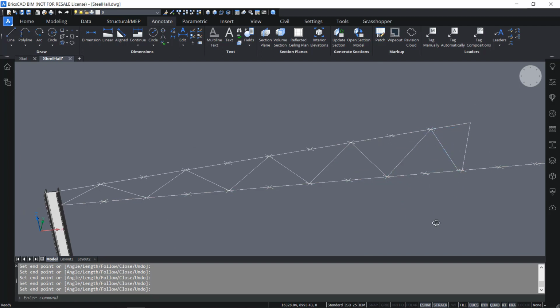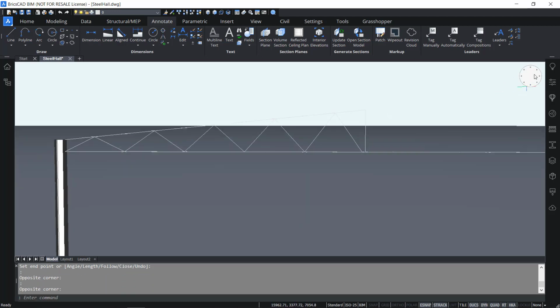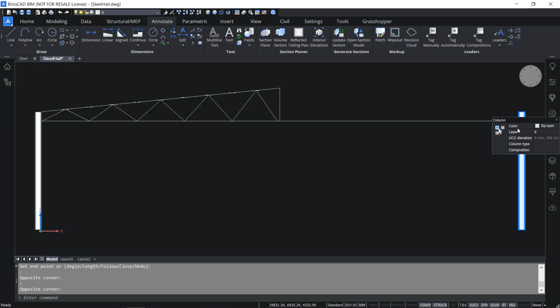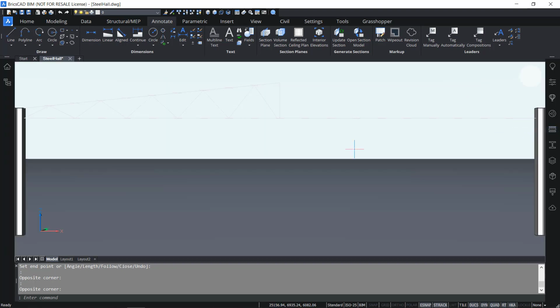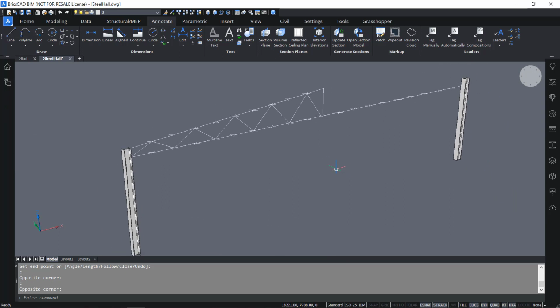Just like this, so that you actually created a truss. I can show you again if I go to the front view and put perspective back off. You will see that now I created a truss, which is good. This is what I wanted. So this is now a truss, but it's only half of a truss. So we will need to mirror the first half to create a whole truss.